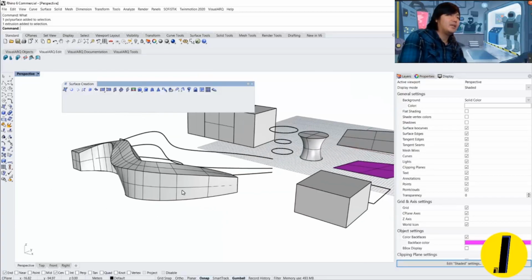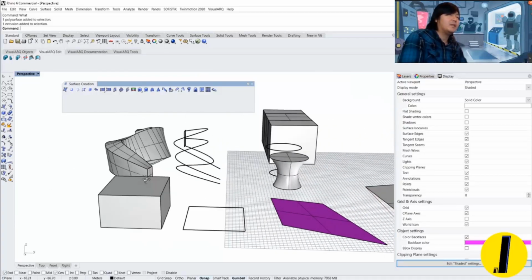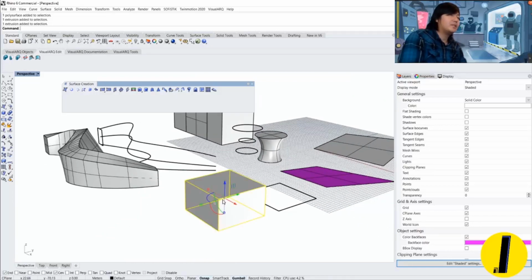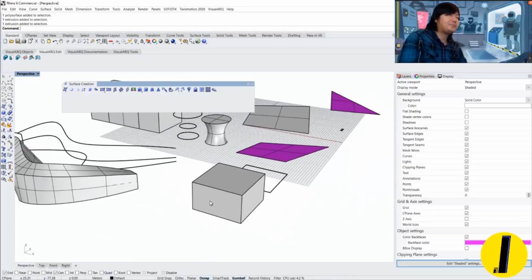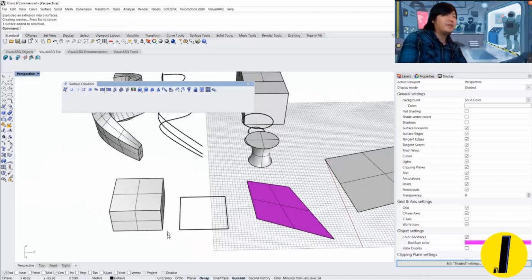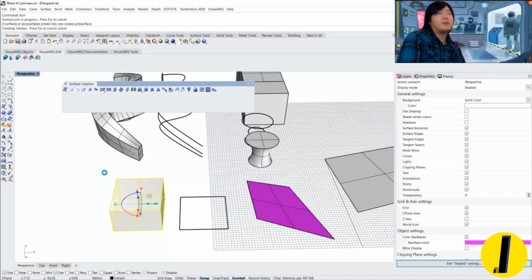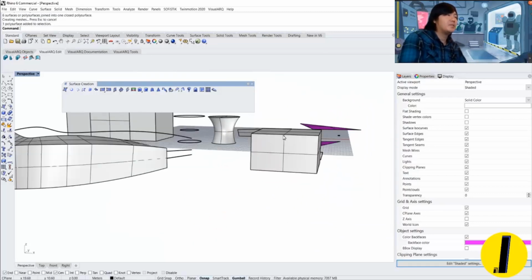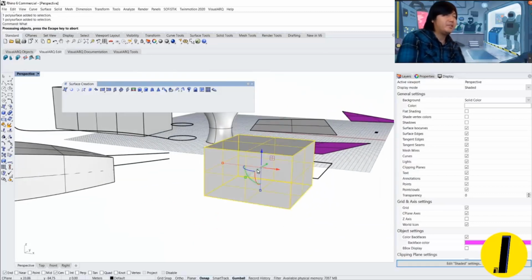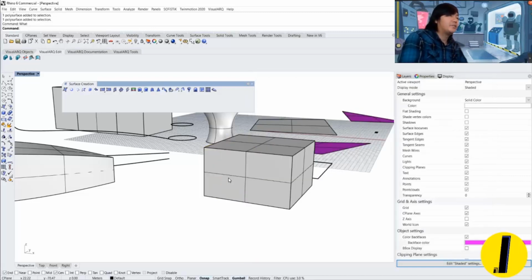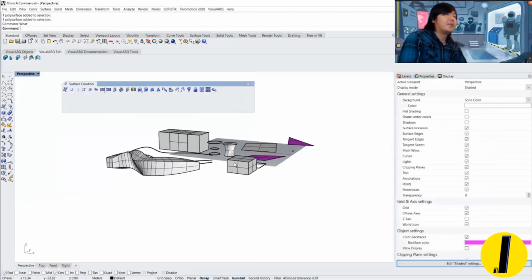That indicates the UV of the surface, but extrusion basically doesn't show this iso curve. So that's the only difference. But you can explode. When you explode, it becomes every single surface, and after that, if you join them again, this becomes a kind of poly surface. So you can see the iso curve between the UV grid.